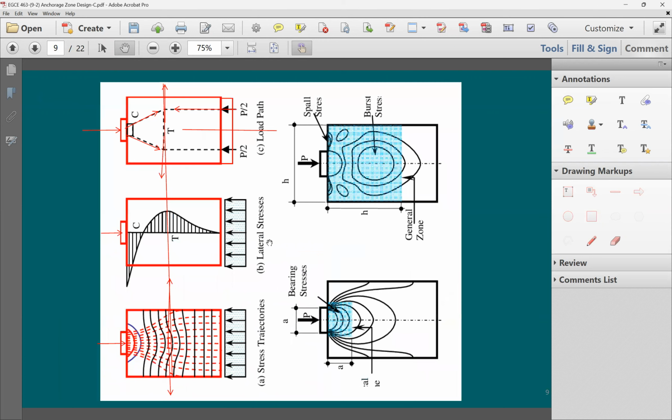Moving forward. So again, if you'd like to do finite element analysis, take this model, and this gives you all the stresses in the Y direction. This gives you the stresses in the X direction. We call this the bearing stress. This can be all compressive stresses. Look at the compressive stresses, it just goes up and up, right? And then it gets more uniform here. At the beginning, it was just localized, and then at this point here, the stress is uniform. Very similar to what we have done here in this stress distribution.